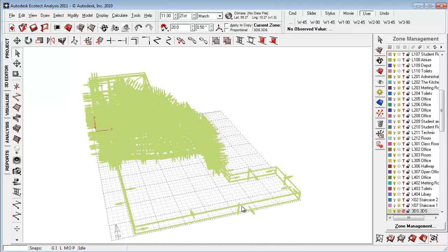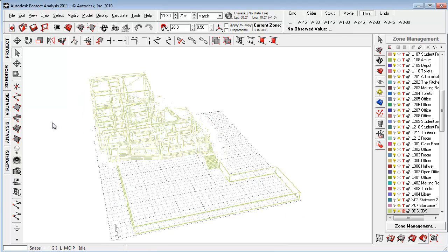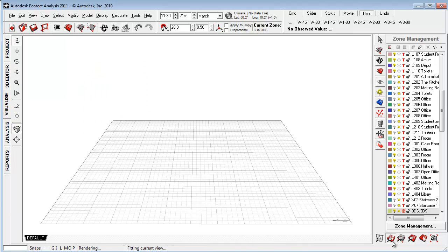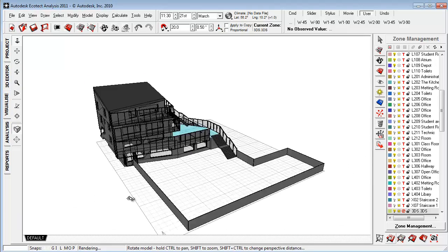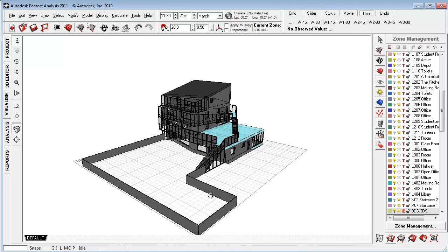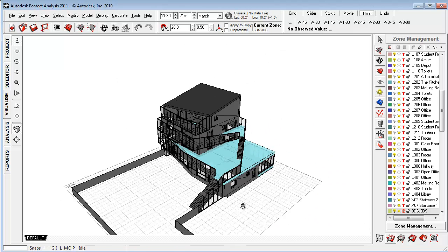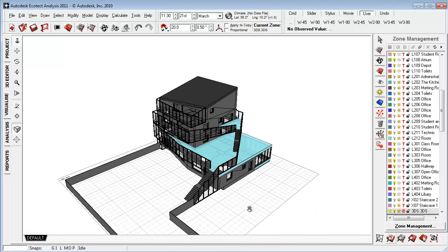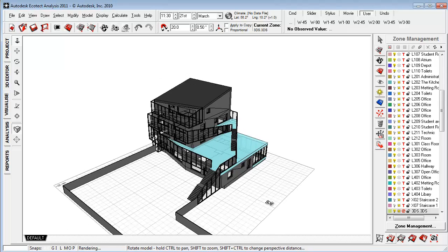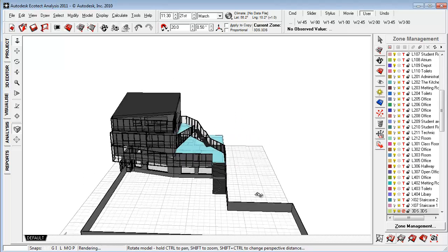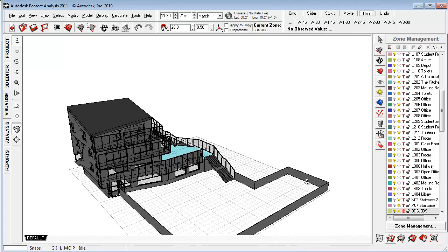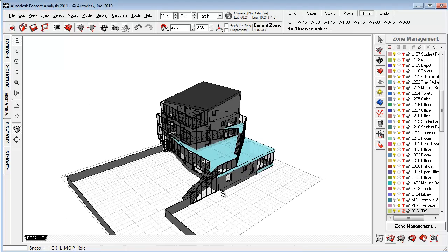So now it's merged all the triangles and the geometry, and I can go in here and just have a look at how sweet this model is brought in using that bit of workaround here. Another way that you can use is that within Revit you isolate walls and windows and stuff like that, and just import the elements in different files, so you'll be able to control and go in and work a bit more with the model.